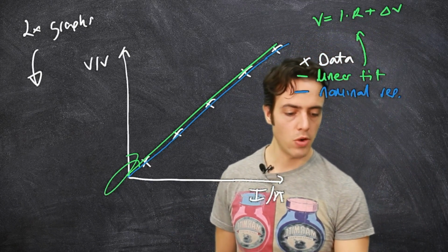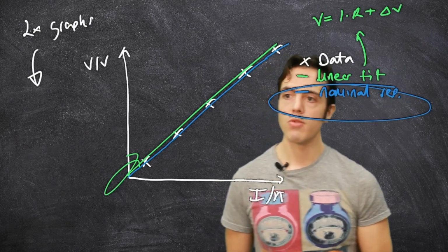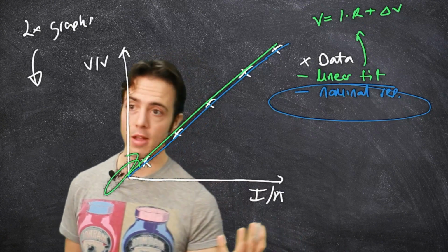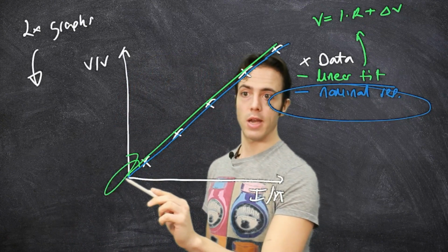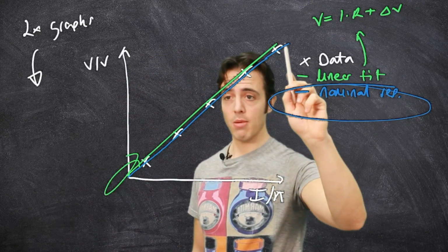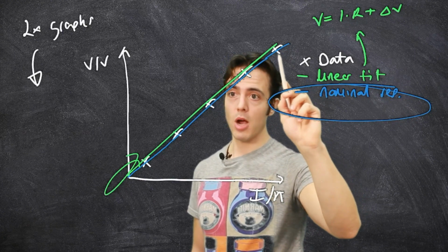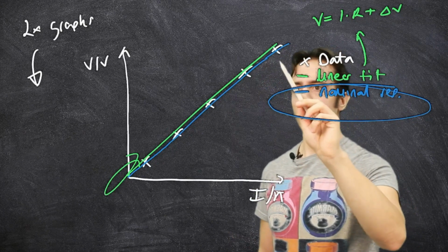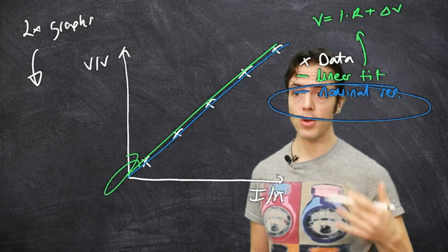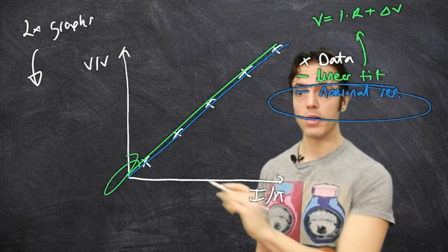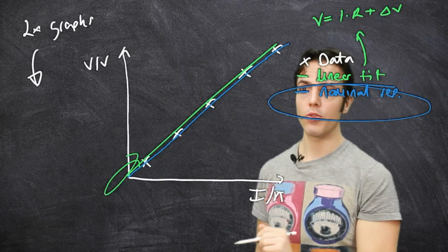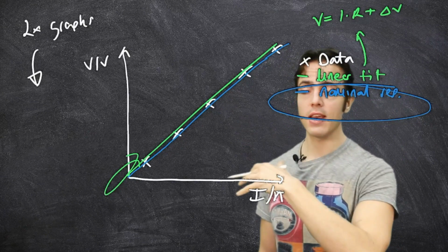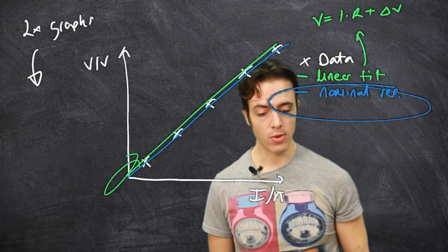We're also going to put a nominal resistance on it. So if the nominal resistance of one of those resistors was, say, 130 kilohms, you'd put an intercept of 0, you pick your maximum voltage, and you'd probably just pick the maximum voltage, divide it by your nominal resistance, and that gives you your maximum current. And draw a straight line joining those 2 points. That is your nominal behavior. And this is a good way of indicating how closely these two tie together.